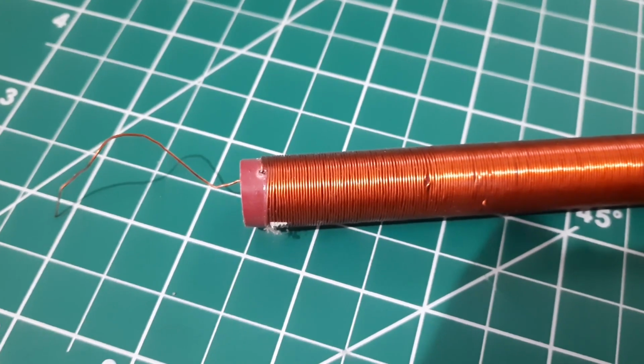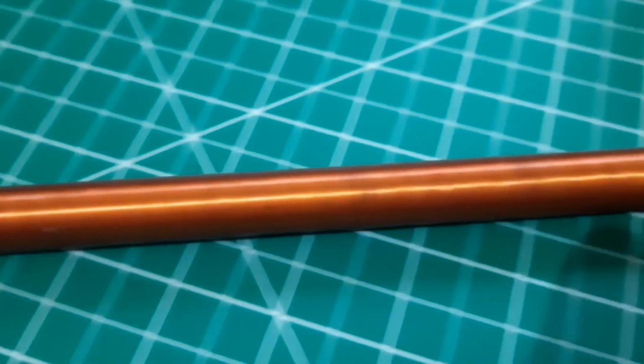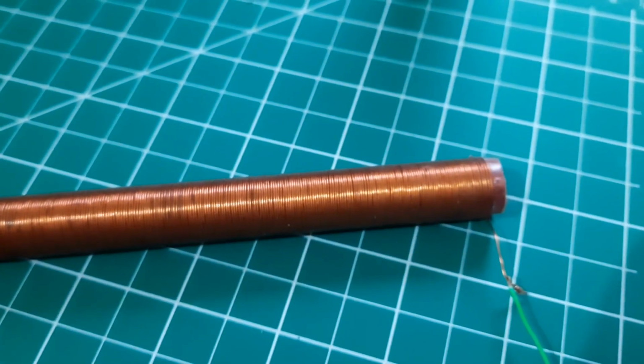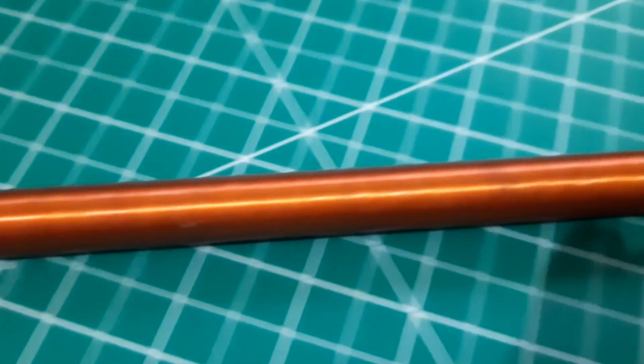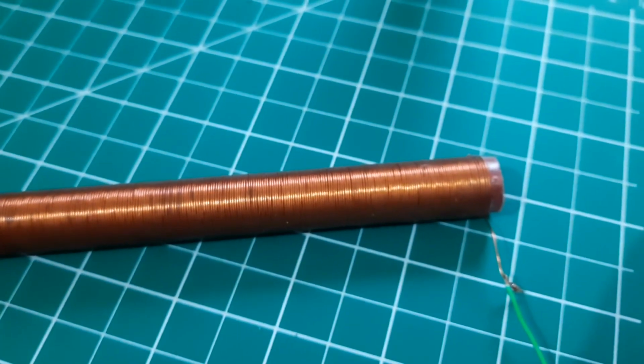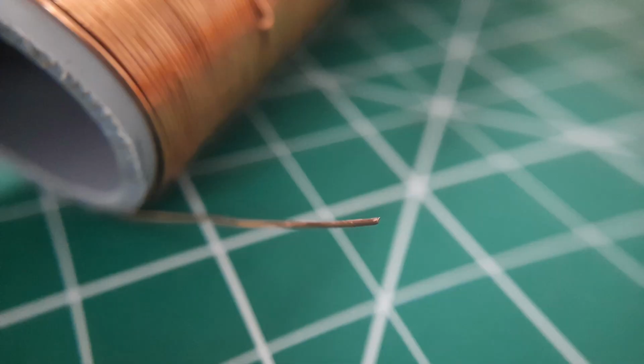Now we can see how to troubleshoot the Slayer exciter circuit. Use a standard size tube and number of turns. Previously I used a thin tube with a large number of turns, which failed to work. Sand the tips of the primary and the secondary coil. The copper coil is enameled, hence remove the coating at the tip before using.